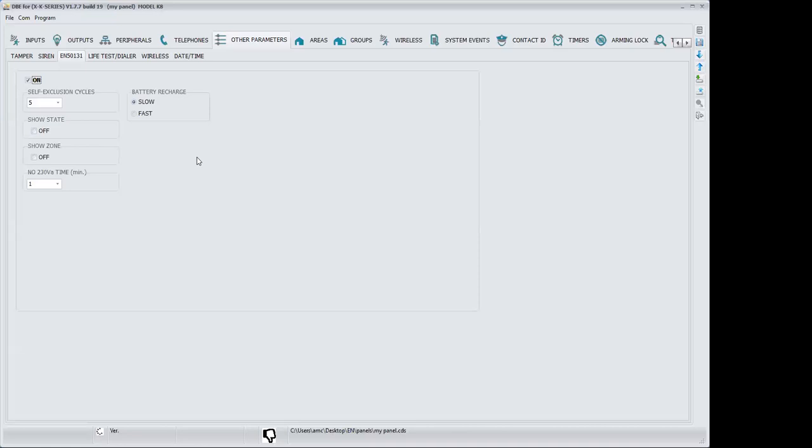If the battery is okay and you don't have an alert from the keypad, try to measure the current, and send me a mail with the result. Normally, if the system is okay, you will see a few hundred milliamps. For standard charge, you will see from 100 to 300 milliamps, not more. Try to check this.